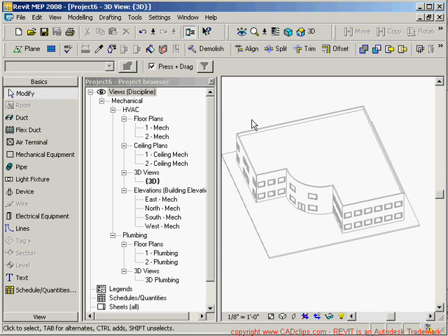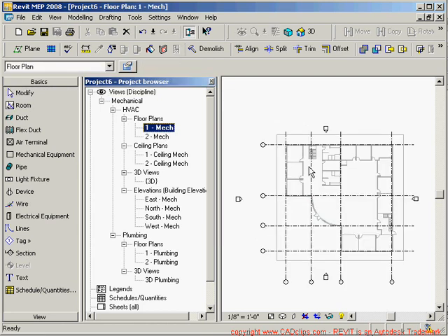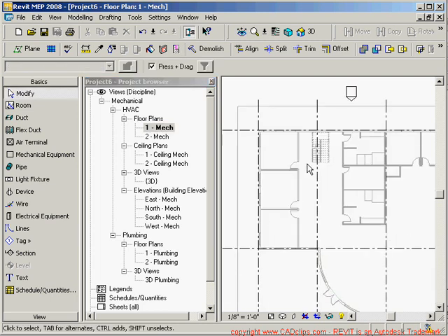So now I've linked in my architectural model, and what I want to do is copy and monitor the rooms, because the rooms are really the lesson of the day. Rooms have all the information with the volume, and when we attach our air terminals and all our stuff, the room holds the data that says how big that room is and any particular criteria about the room. So we want to copy the rooms from what was already in that architectural model. This is one way, of course, to do it, because we can use the tools that are built in out of the box here.